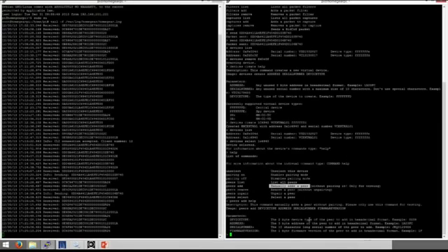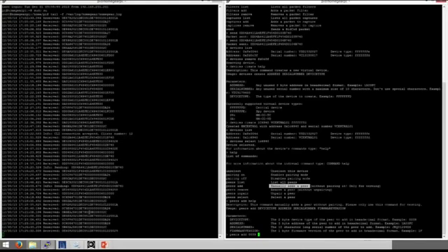Peers add. Now we need the device type first. The device type you can find in the XML file. The device type of the thermal control is 39. Then we need the address, which was 1DE790. Then we need again an arbitrary serial number. We call it virtual thermal control 1.